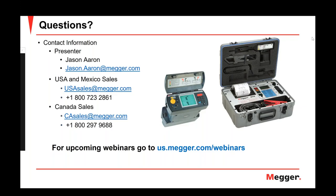If you have a valve regulated lead acid battery, for example, that you have no access to the electrolyte, the best way to get the temperature is going directly to the negative post of the cell or the cells that you want to measure. The negative post is where all the chemical reaction happens, and if there's any internal activity in the battery, the temperature will be increased mainly on that terminal post. So that is the best way to go for the temperature.